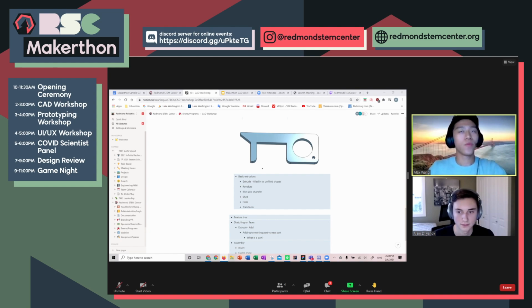If you click this tool, the first thing it's going to do is give you this highlighted blue region. Like in the sketch, this query box is what it needs for the tool to actually work, and it's asking for faces and sketch regions to extrude. It's pretty self-explanatory. And so you click the profile that Alan just made, and boom, now it's a 3D shape.